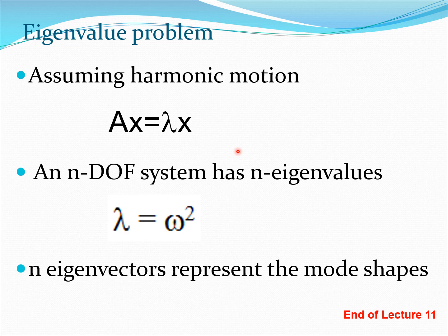Now it does not matter whether you got this from a typical free body approach like we did today, or you use some more complicated computational mechanics method to do this. So you could use FEM, for example, or some different discretization methods, as long as you get the mass and stiffness matrix and they are in a good form in terms of symmetry and positive definiteness, you can very easily calculate the natural frequencies and the mode shapes of the system.